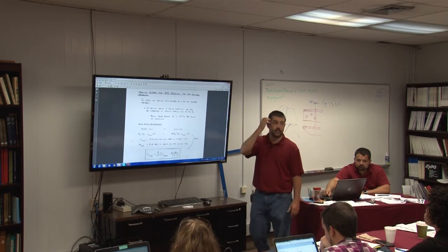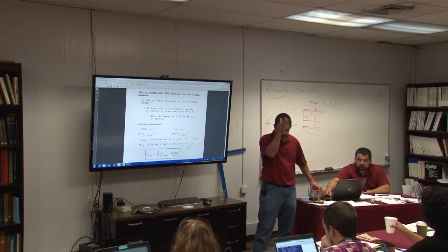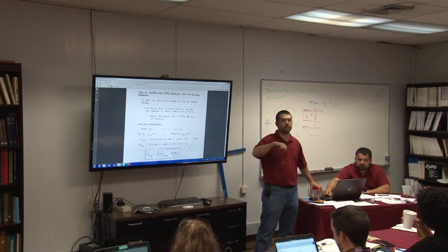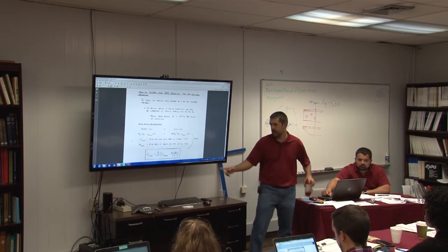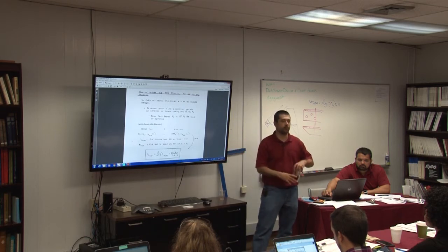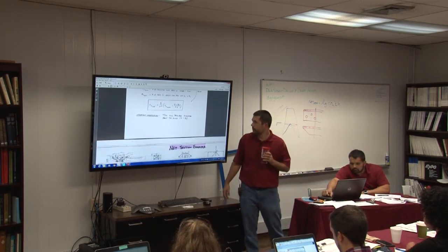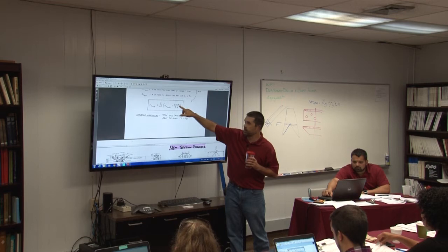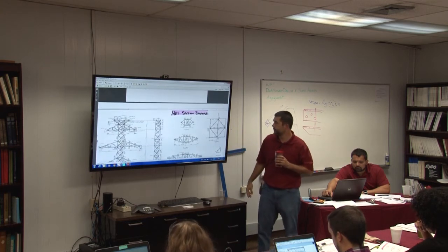This is very, very rarely done. But at times, you may have something that's only overstressed in that section. And if you look at it and say, well, I'm saying there's two holes in the middle of the member, but it's connected on one leg, then Tower is actually over-conservative because it's not applying the full yield strength to that section. And you can back off the number of holes and get a more refined analysis. I mean, you can do a hand calculation too, but you can get Tower to do the calculation this way. The only difference is this calculation requires knowledge about the angle. So you'll notice there's actually the thickness and gross angle area in this calculation that doesn't exist in any of the others. That's one of the only differences.